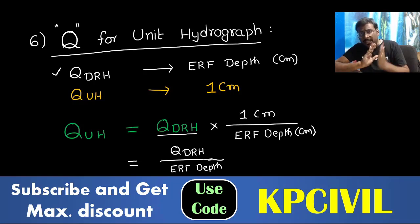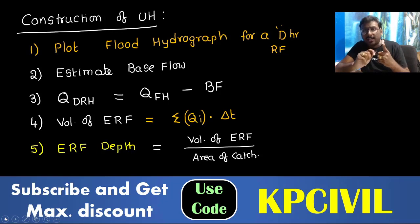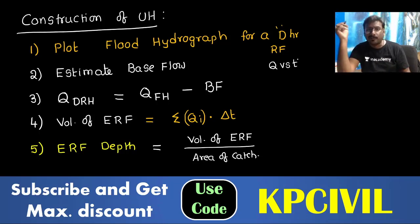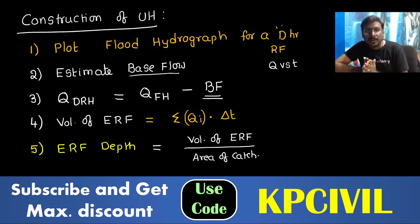So by using any kind of flood hydrograph, step by step, first you plot flood hydrograph ordinates, discharge versus time, discharge on y-axis, time on x-axis. Then after plotting you write Q1, Q2, Q3, Q4. Then estimate the base flow and subtract it, to get direct runoff hydrograph ordinates QD1, QD2, QD3, QD4.